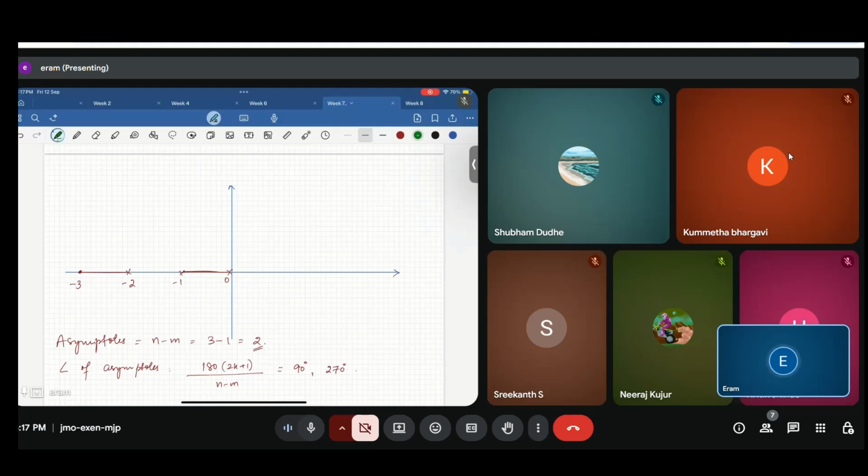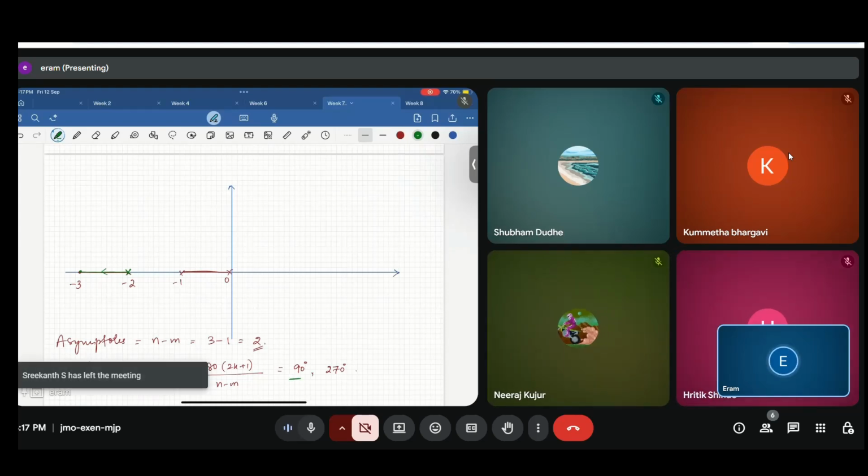From here you can guess that since one branch from an open loop pole will converge to this open loop 0, the asymptotes having angles of 90 degrees and 270 degrees will for sure originate from the other open loop poles. So our root locus will go to infinity by making an angle of 90 degrees from one pole and 270 degrees from the other.